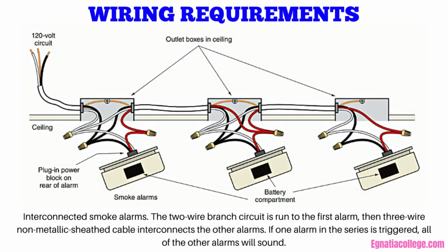When using interconnected smoke alarms, it is important to refer to the manufacturer's literature for the maximum number of devices allowed. Each manufacturer and model may allow different maximum numbers. When devices are interconnected, all alarms will sound at the same time, regardless of which device actually detected smoke.